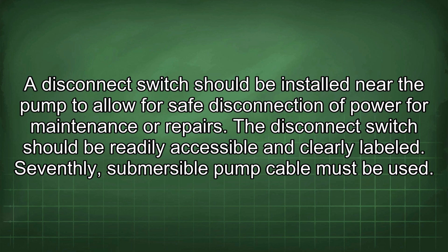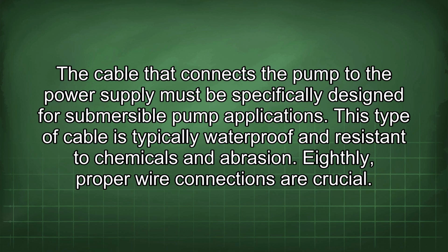Seventhly, submersible pump cable must be used. The cable that connects the pump to the power supply must be specifically designed for submersible pump applications. This type of cable is typically waterproof and resistant to chemicals and abrasion.